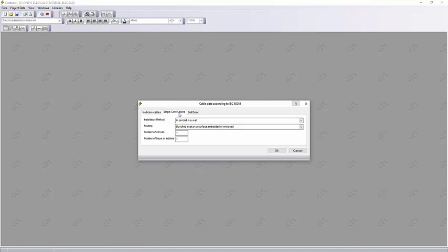In case the user has selected the method of calculation according to IEC 60364 standard, then the following information on the cables of the specific installation has to be defined. By using this table, the user can define a set of typical load types, to be used as templates. For each typical load type, the name of which is inserted in the first column of the relevant screen, the following characteristics can be provided.